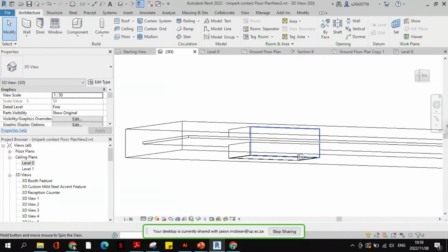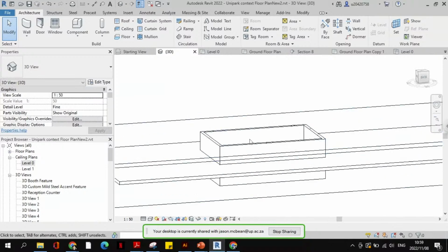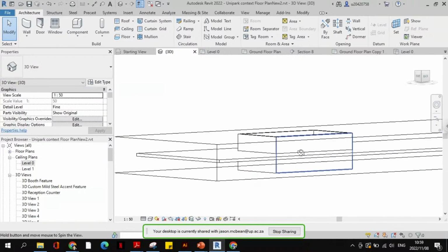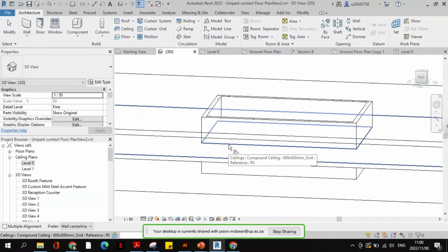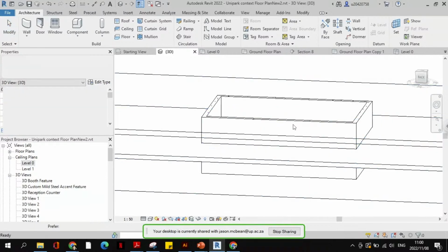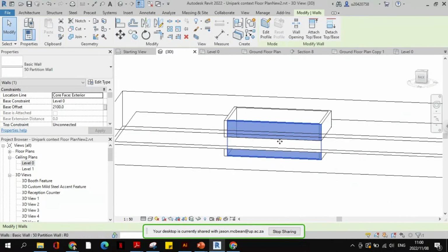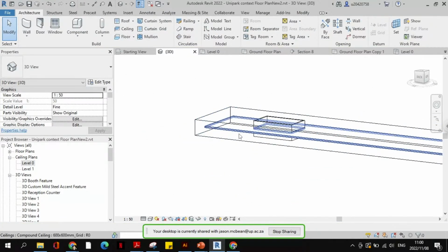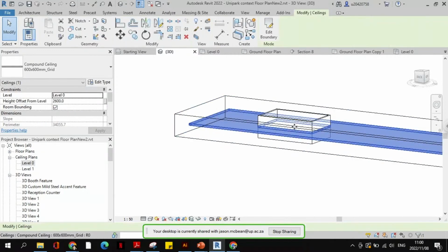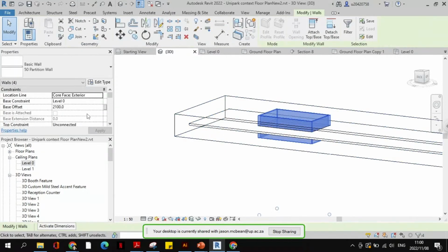But now what's cool is, can you close it? Now watch this. So now what you do is you just say apply, align. So here I'm going to say that, so this back of wall, I need to align these. It's cutting with the section plane, so I've made that too high. But if I grab the ceiling height, it's 2600. Watch this. I grab all of these, and I'm going to say 2600. I might have to extend them a bit more.